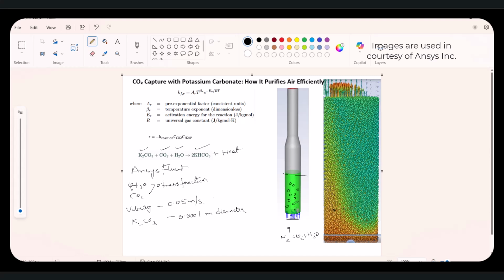And I'll try to patch this region entirely with these particles. So each cell I'm trying to patch with one particle, and I just want to make these particles stagnate. So even though airflow is there, the particles won't move because the air velocity is a bit low. So I'm assuming these particles will stay at their location. In order to make them stay at their own location, I'll incorporate a UDF saying that it should not move.